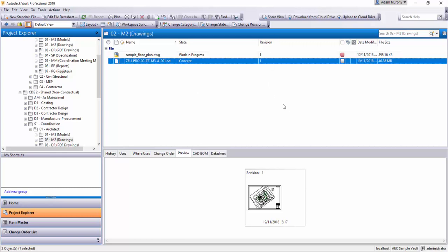So you might ask yourself, why do I want to manually download every file one at a time? And the answer is yes, if you're doing it manually, you should be doing every file individually. But additionally, there is a function hidden away in the administrator settings in Vault, where you can set up a schedule which will download all the files, say at the end of the evening when you're finished working with your project for the day in BIM.